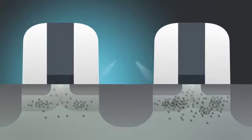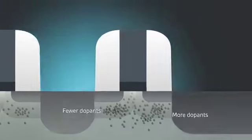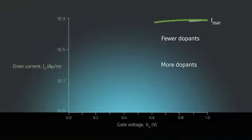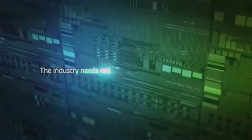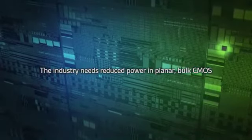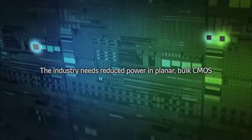Traditionally, designers compensate for VT variability by using a supply voltage that is high enough to turn all transistors on and off cleanly. But this voltage overdrive wastes a tremendous amount of energy. To get past this power roadblock, the industry needs to rethink the CMOS technology that has driven the industry for decades. But what if it were possible to reduce the power in planar bulk CMOS? Suvolta has invented a device technology that does just that.